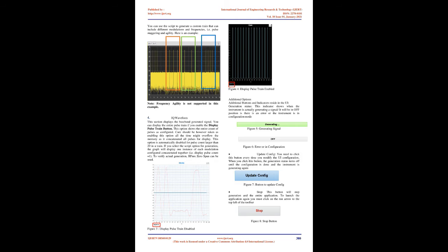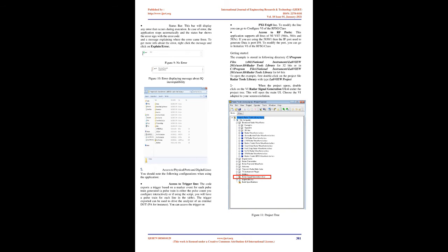Selected pulse modulation. Modulation-specific parameters such as pulse duration, IQ rate, BW, ratio, order. Pulse count. This option allows configuration of pulse train. The count represents the number of consecutive pulses distant relatively to the configured PRF.